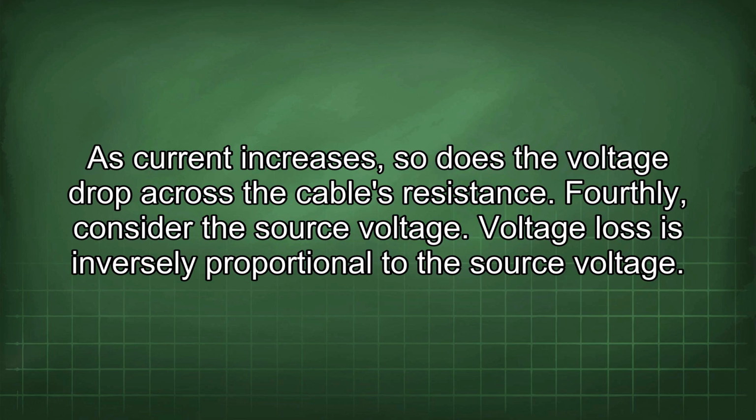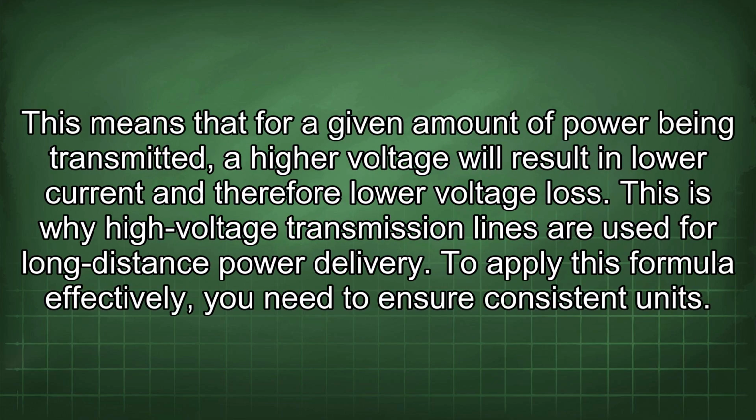Fourthly, consider the source voltage. Voltage loss is inversely proportional to the source voltage. This means that for a given amount of power being transmitted, a higher voltage will result in lower current and therefore lower voltage loss. This is why high voltage transmission lines are used for long-distance power delivery.